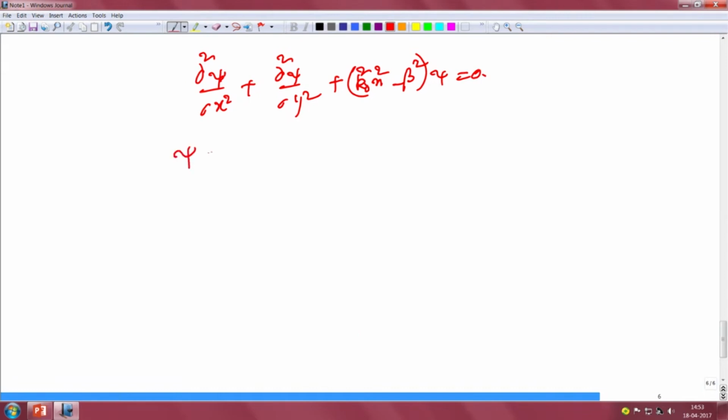So, the psi represents the mode field, and along with beta characterizes the mode. So, the mode has got a field pattern and the propagation constant, and I have shown the 2-dimensional form, x square and y square. For a channel waveguide you have both the components, and if we are talking about a 2-dimensional waveguide like a slab waveguide, we can ignore one of the variations like y.